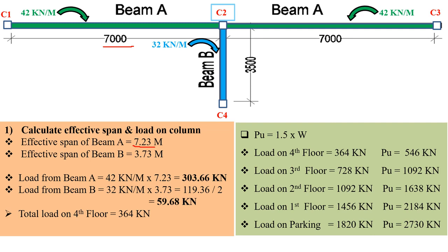7.23 meters. Similarly, for the beam of 3.5 meter, with a 230 mm support on this side and a 230 mm support on that side, the effective span will be half of this and half of this. So it becomes 3.73 meter. Now the load is already given, that is 42 kilonewton per meter. So it is a per meter unit weight, right?